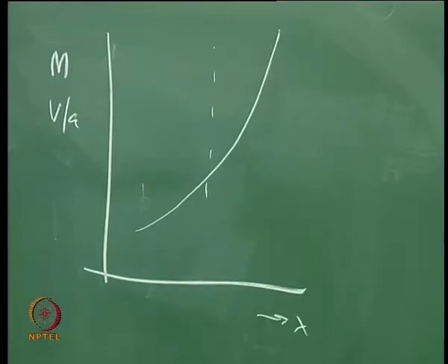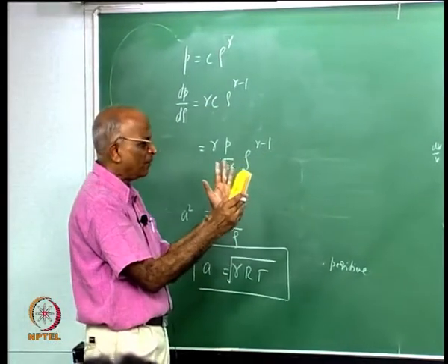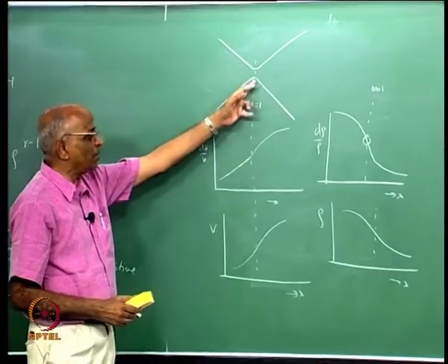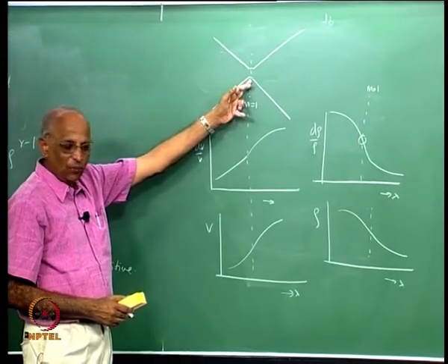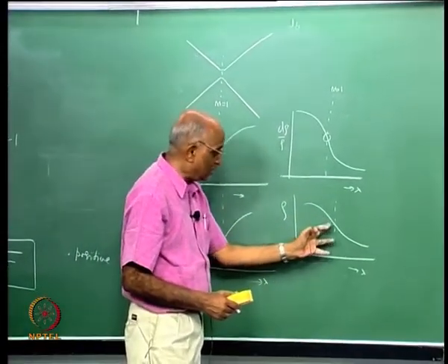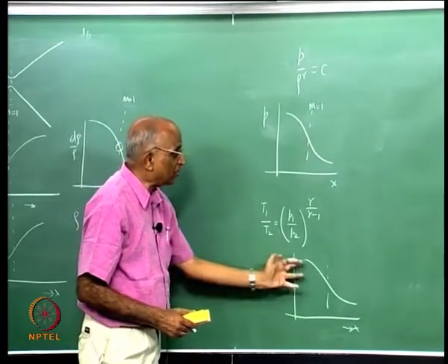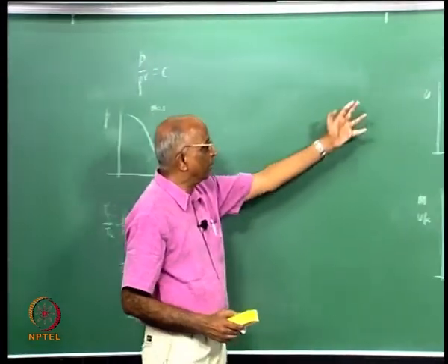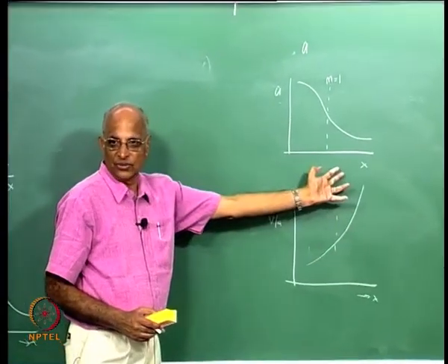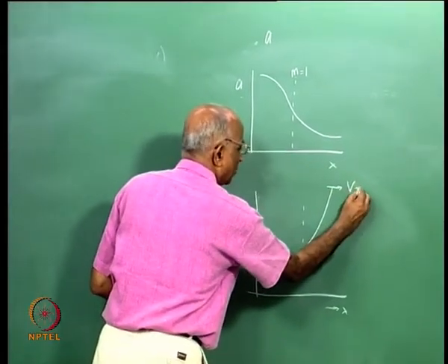I think this is fundamental to any nozzle flow, any expansion, and we must remember this. Therefore let me repeat it again. dV by v progressively increases when I have Mach number 1 at the throat, velocity increases, the density decreases rapidly at the throat, pressure also decreases, temperature decreases, the sound speed decreases along the length, and therefore the Mach number increases along this. And we are interested in a high value of Mach number or jet velocity at the exit.